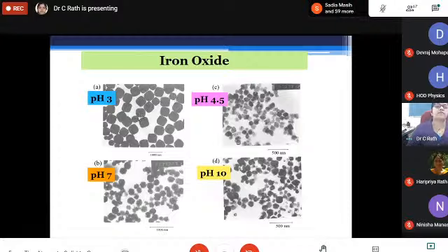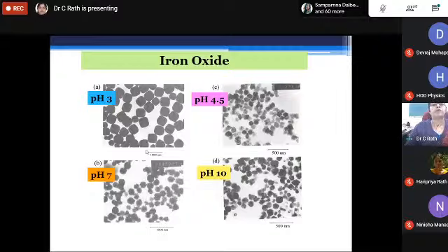One can see here generally coercivity is inversely proportional to size. Here the size is almost 650 nanometer, and this pseudocubic particle shows around 3000 to 6000 Oersted of coercivity. However, these are very small particles where one expects large coercivity, and it shows around 600 or so.